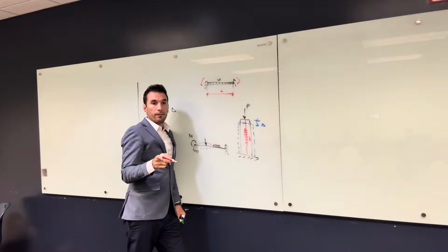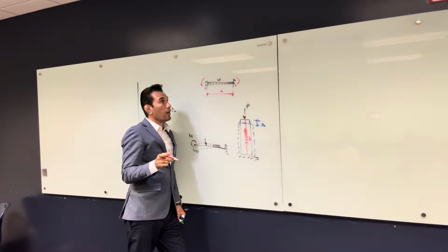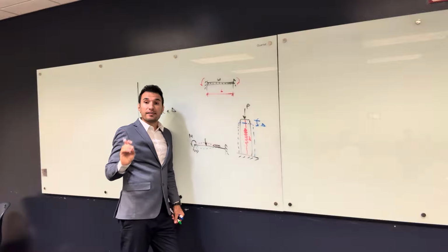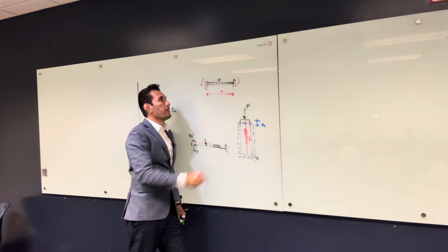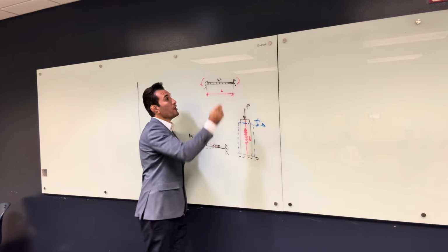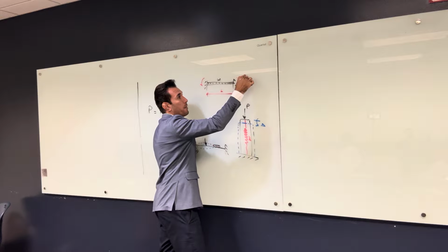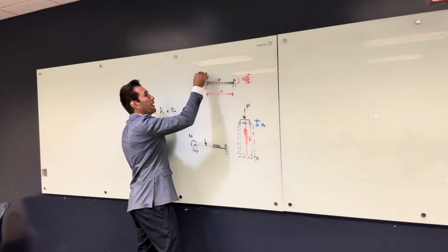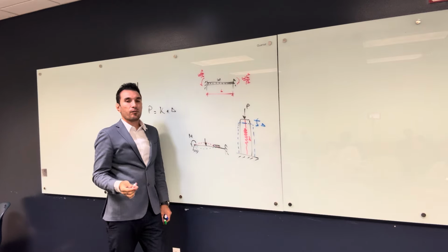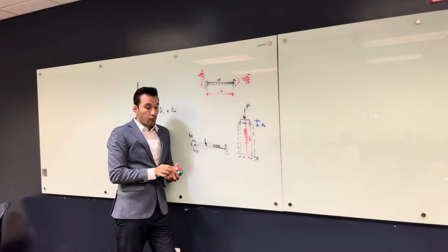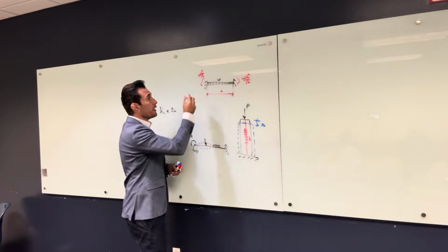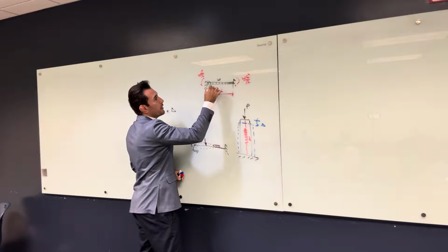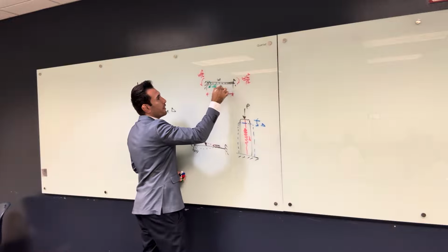I don't remember. It's W and L. Definitely it's going to be a function of W and L, right? So if we have a simple beam, what is the moment in the middle? It's WL squared over 8, right? So this one, remember, is WL squared over 12, okay? And this one is WL squared over 12. Is that reaction or action? Reaction, right? This reaction is coming here because there's an action here. This action is equal to WL squared over 12, and same thing.